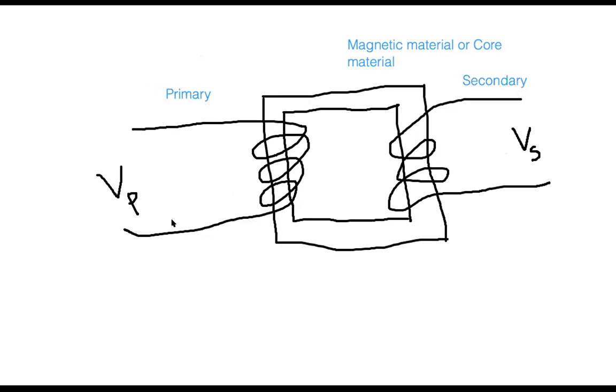That is the main point. So I am discussing the transformer. Everybody say I am talking about the transformer. So how does this work? We have two sets of coil, primary and secondary, mounted on the same magnetic material. First I apply the voltage on the primary side, which is VP. And keep in mind, everybody, of course this is the AC voltage. We cannot apply DC voltage on the transformer. I will answer that point, why, soon. First, let's assume that this is the AC voltage VP.